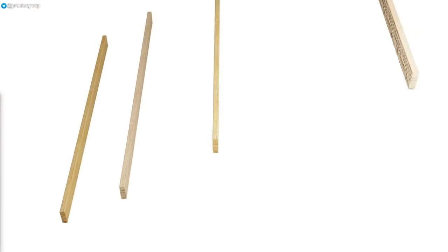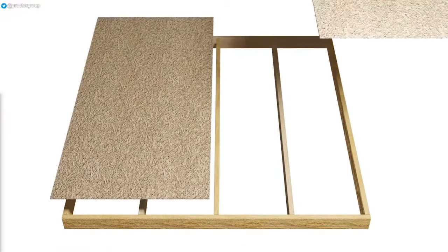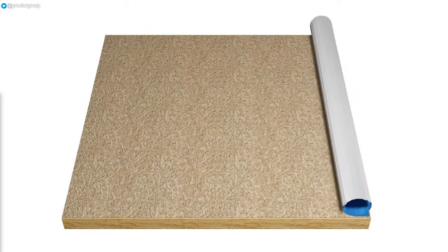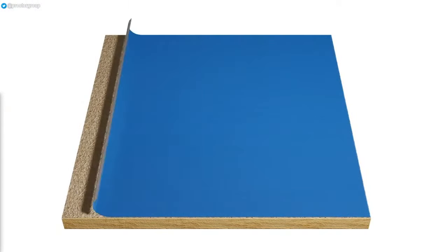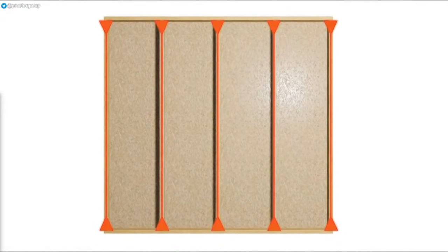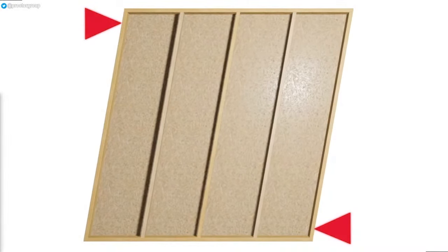This is the original type of off-site timber framing, the classic kit house. These structural panels are partly fabricated in factories, but with a substantial degree of on-site finishing required. The studs and sheathing boards are assembled in the factory, and the panels are fitted with external breathable membranes for weather protection, but the panels are then left open, meaning that insulation, services and internal finishes are installed on site. The studs in this type of panel are the main load-bearing members, transmitting vertical structural loads, while the sheathing boards prevent the studs from twisting and moving.